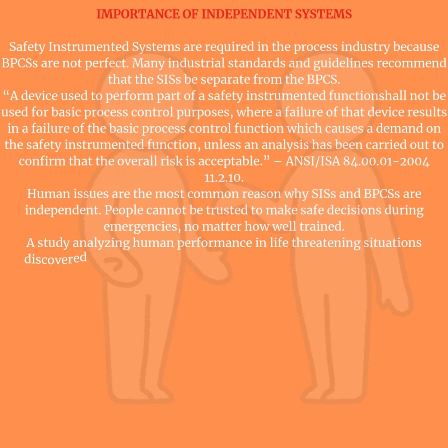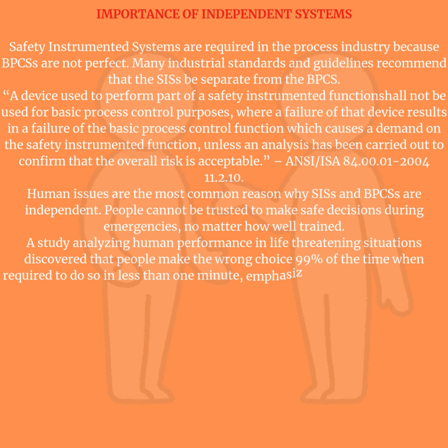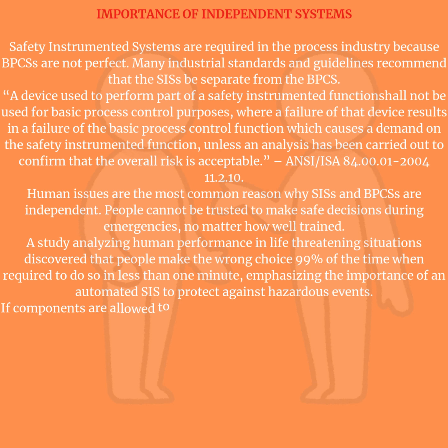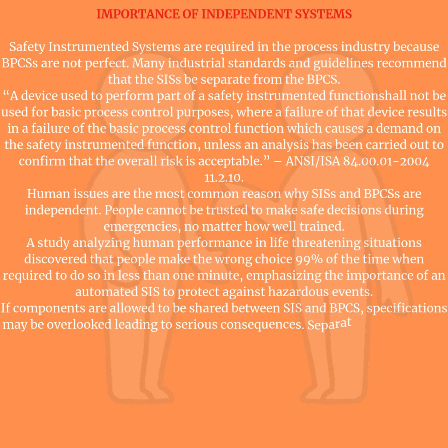A study analyzing human performance in life-threatening situations discovered that people make the wrong choice 99% of the time when required to do so in less than 1 minute, emphasizing the importance of an automated SIS to protect against hazardous events. If components are allowed to be shared between SIS and BPCS, specifications may be overlooked, leading to serious consequences.